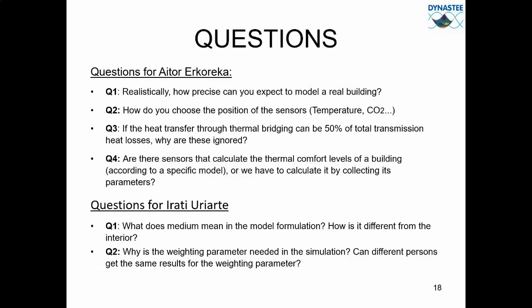So when you make energy balances of the whole building, you are actually considering the thermal bridges within the parameters you estimate in that building, such as the heat loss coefficient. So we are actually not ignoring this thermal bridging using the techniques you are learning in this course.